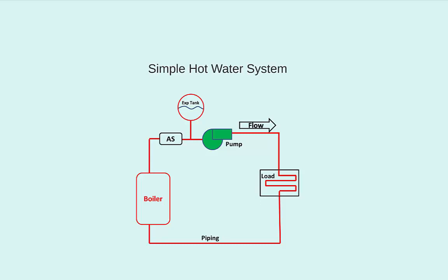As the water whips around the inside of a pump, there are locations inside of the pump where the static pressure of the water can drop to a point where it is at risk of water evaporating from the liquid state into a gaseous state. Eventually, those water vapor bubbles will encounter a location in the pump where the static pressure is a little higher, and those bubbles would subsequently collapse.